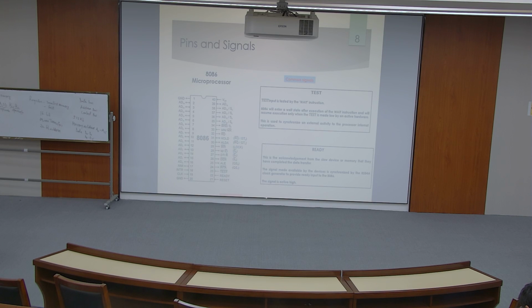Now, the signal is made available by the device, and it is synchronized by the 8284A clock generator to provide what we call the ready input. So this signal is active high.